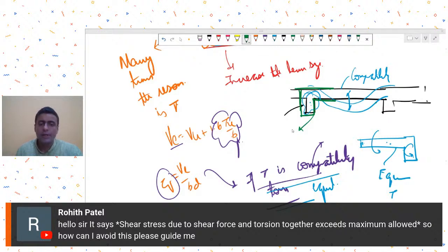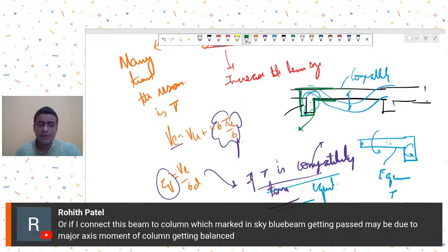So long answer short, if your beams are failing in torsion, you need to judge first as a structural engineer what is the reason for this torsion failure, what nature of torsion it is, and then you assign the torsion modifiers.